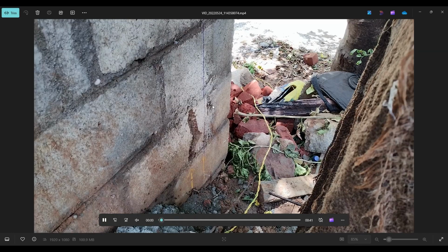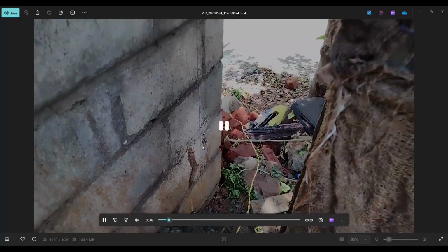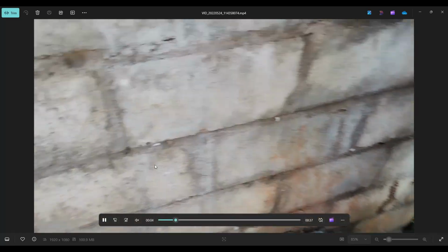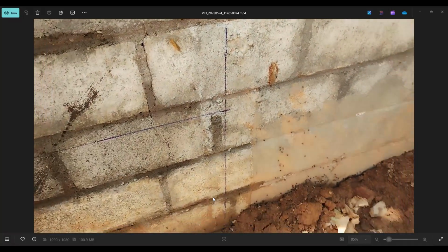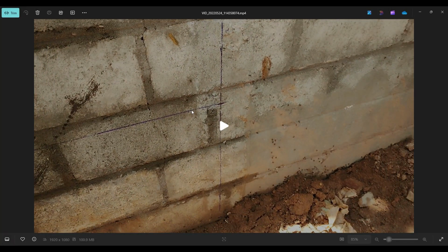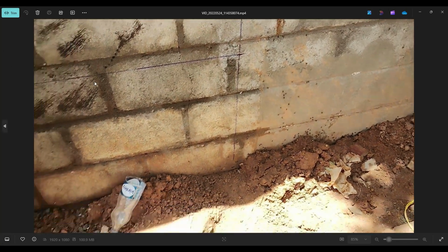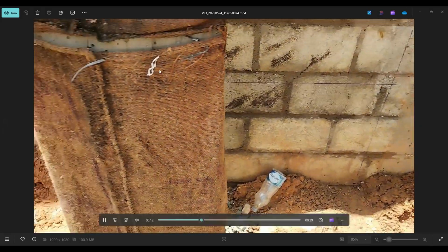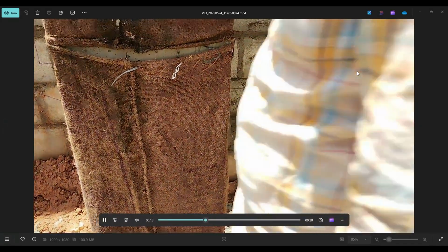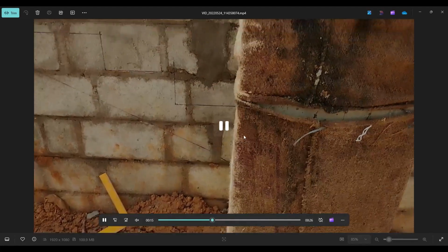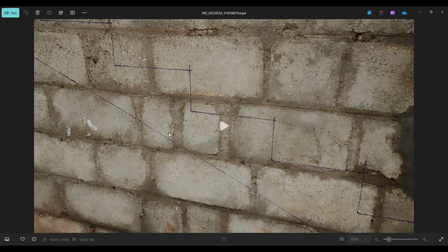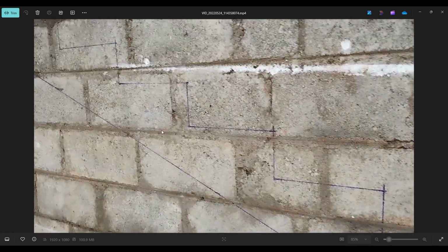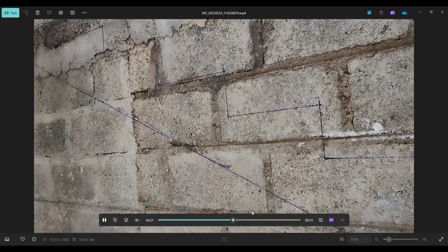I'll show you this particular staircase only. You can see this is the very first grid line. From this grid line they have gone to a distance from where the staircase will start. This is the mark. From here, at a height, we have a landing. After the landing, the one single staircase will be stretched all the way to the top. So they have marked that landing height, and from that landing height they have marked all these other things. And the way we had marked our 6-inch waist slab, they have also marked the 6-inch waist slab. So you can see, this is something that they have done on the site.